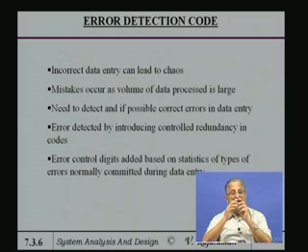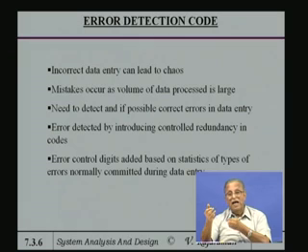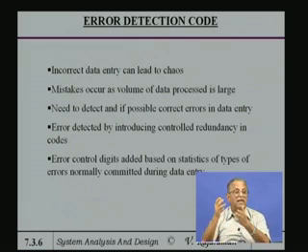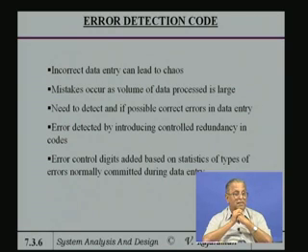Okay. Similarly, if you use a code like a decimal number, then instead of parity bit, I must have an extra digit, which is an error detecting digit. It is also possible to have error correction, but as I said, redundancy becomes too much, and so normally people are satisfied with error detection. So you have a controlled redundancy, that is one extra digit. See, if you have an 8-digit number, you add one extra digit.